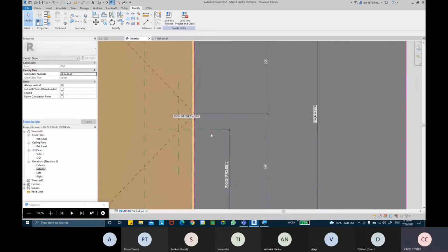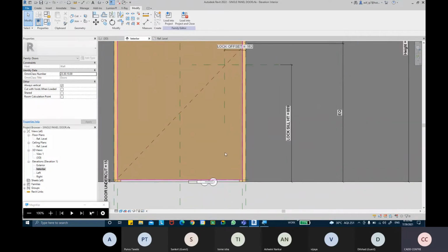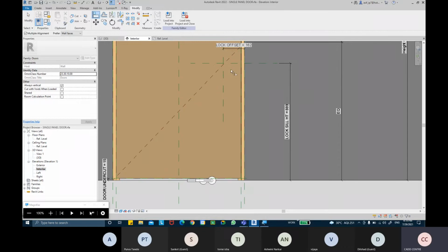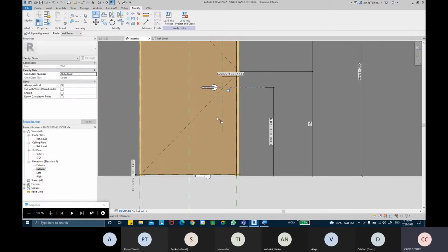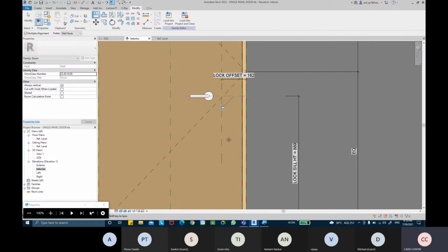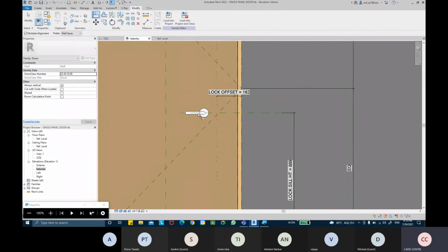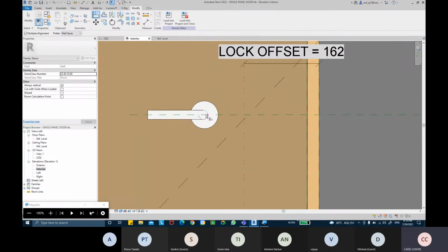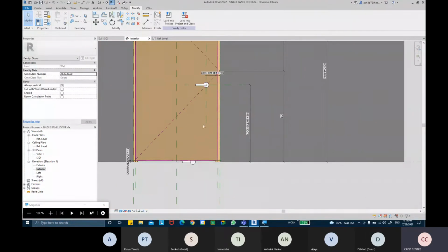So we'll come to the interior view. Well, it's at the bottom; basically both the handles are at the bottom plane. So you can take the align tool, this horizontal plane, and the model sketch line. We'll press Tab. Here we go, and don't forget to lock it. Then we'll take the vertical plane and the center of that lever, and lock that. Now it's placed over there.